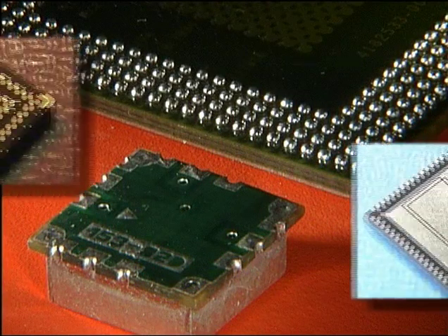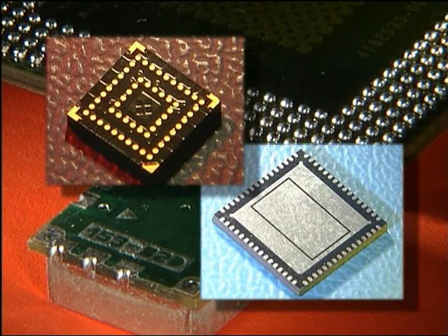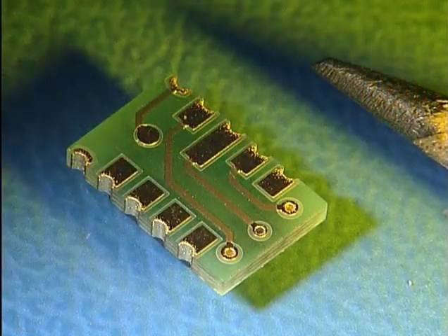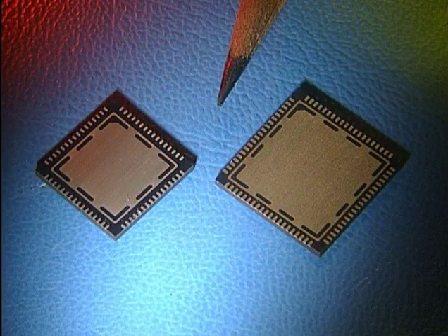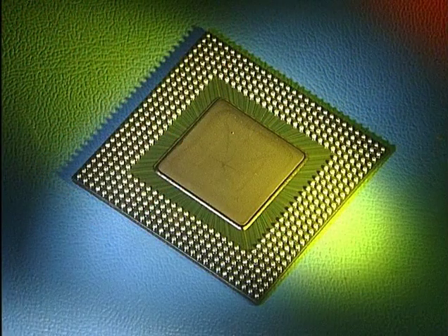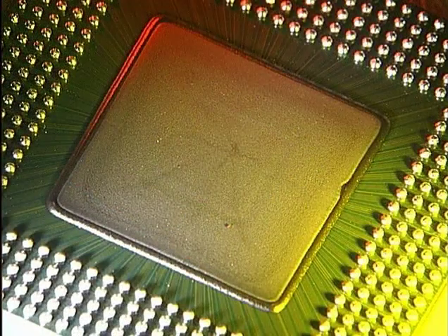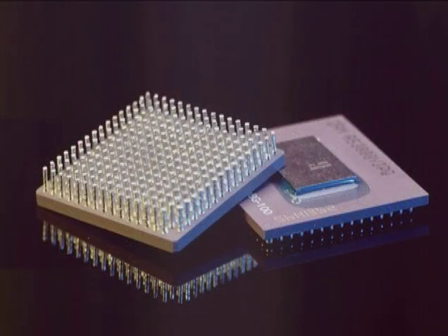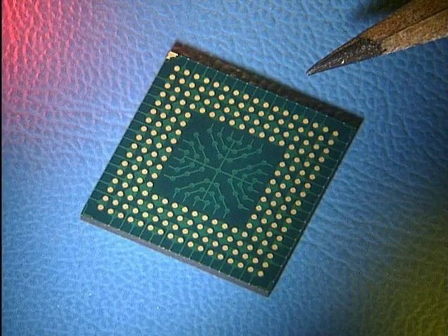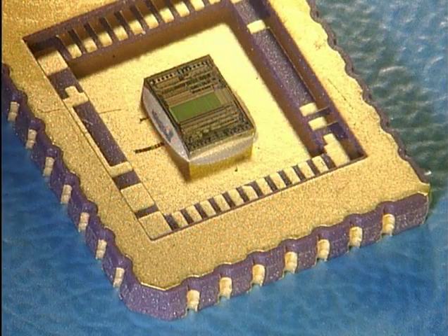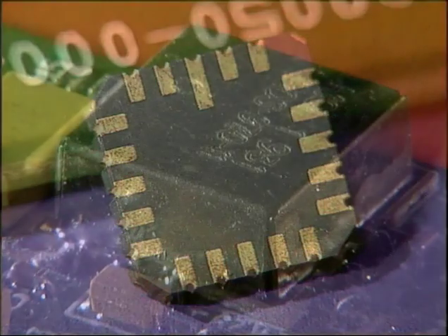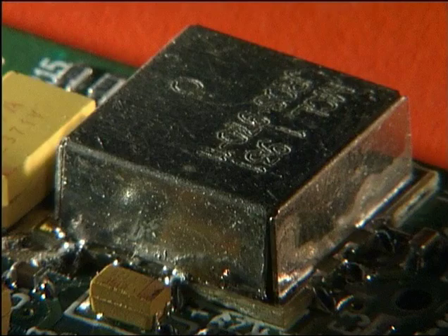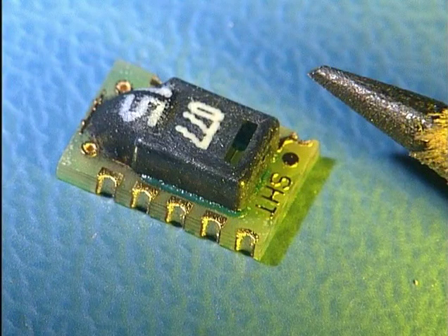Next, let's discuss some of the large-scale leadless ICs. These include leadless chip carriers, or LCCs, QFNs, and the array-style components, BGAs, CCGAs, and LGAs. LCCs are most commonly used in aerospace applications because they are extremely rugged. Smaller, hybrid varieties are currently being designed and used for military and telecommunications applications.